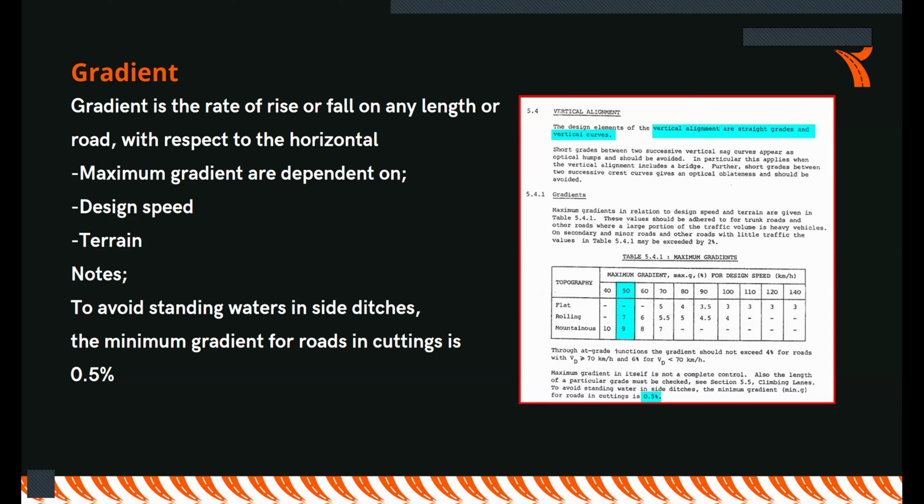And there's something that is called economy of transport. You will notice that when you're driving uphill, you will consume a lot of fuel because the vehicle requires a lot of torque. So in such a case, that's why you find international trunk roads or major roads, the government would rather invest in a lot of earthworks to cut and minimize the slope as much as possible. Sometimes even have tunnels, sometimes even have underpasses to make sure that the cost of transport is very low to achieve these slopes that we are having here. So any design must be able to achieve this slope.